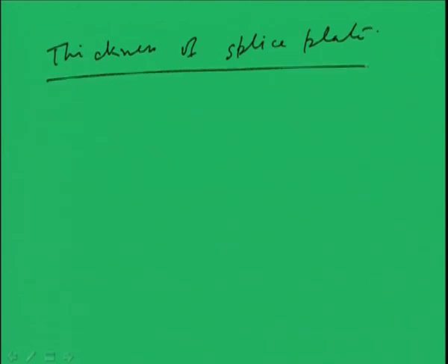Okay. And now the thing is that we have to find out the thickness of tension splice, thickness of splice plate. Okay. There are 2 ways we can calculate the thickness of tension splice. One is, let us assume and we will check whether the splice can take that much load or not. First we will assume, say, let thickness of splice plate be say 10 mm